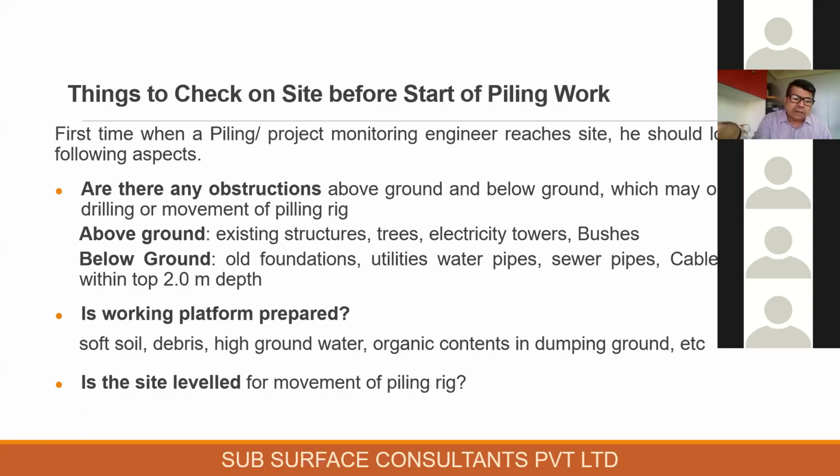In all these areas, about 30 to 50% of the material is organic content. When you add soil on top, or apply machines on that, they will suddenly sink, because organic material is very spongy. So the working platform prepared is a very important consideration.